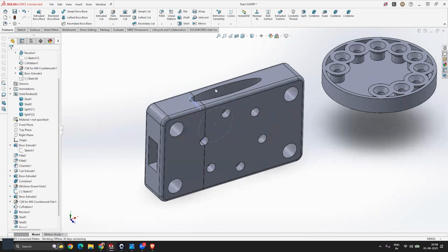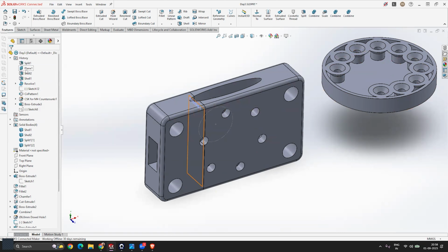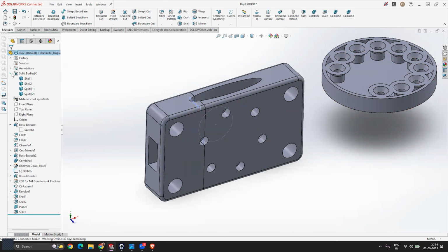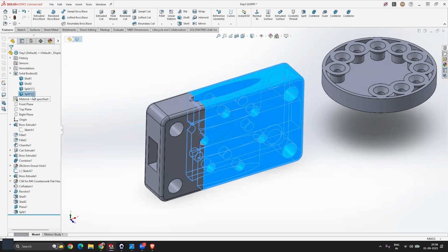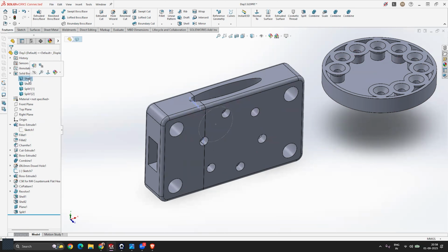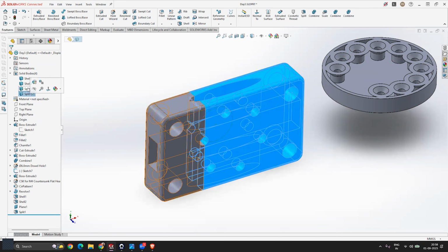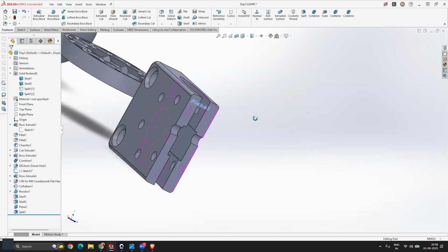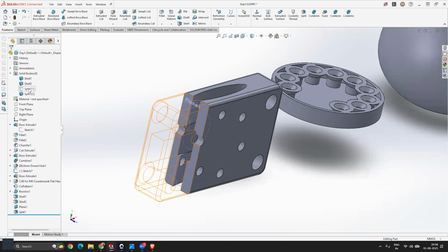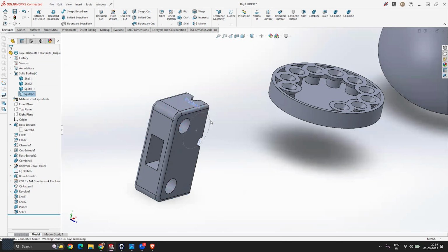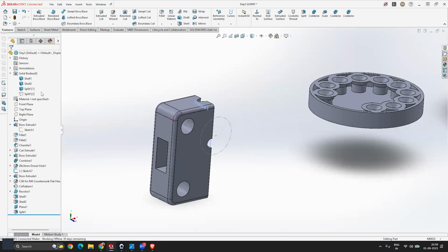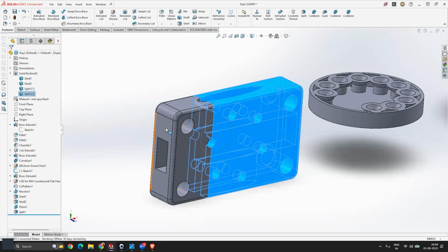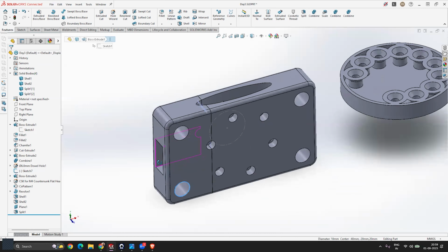And now the same body, if you go onto the solid tab, if you remember, we have a solid tab, and you can see the same single body, earlier it was a single body, got divided into 2 different bodies, that is split 1 and split 2. So if you turn off any of the bodies, you can see we have 1 different body. This is split 1, and I can turn it on again. I can turn it off this time, this one, and this is the second body. So what I did, I had split the available body into multiple bodies.